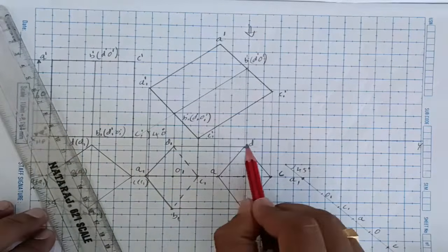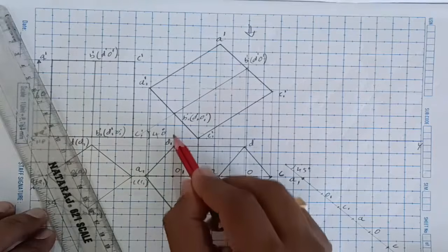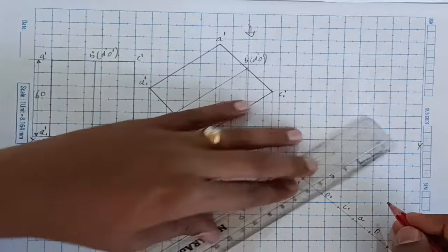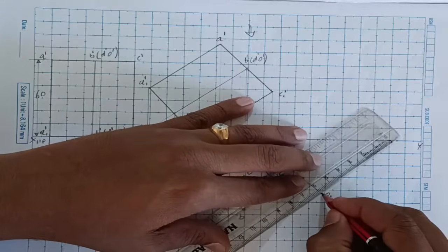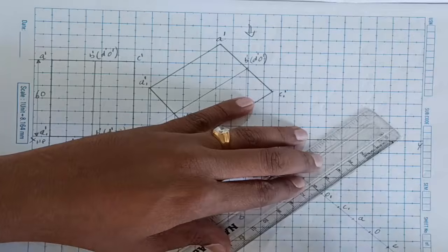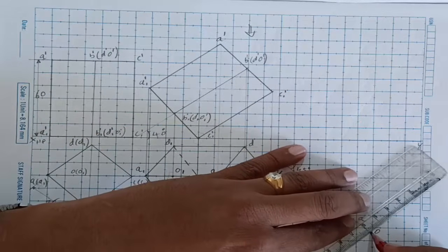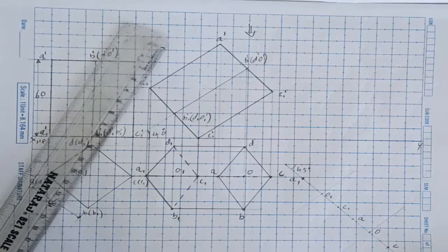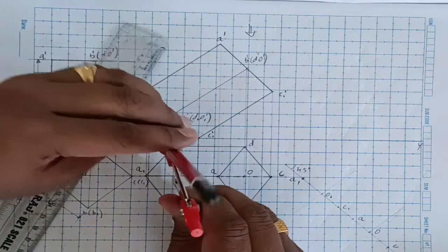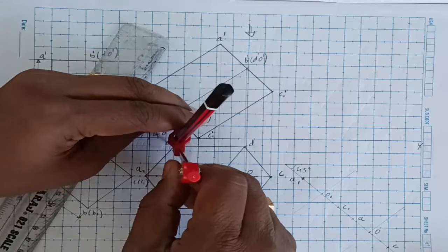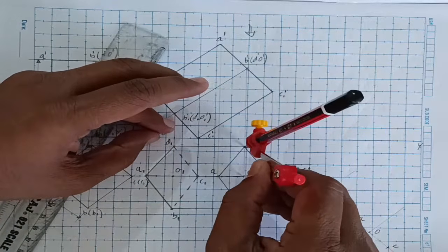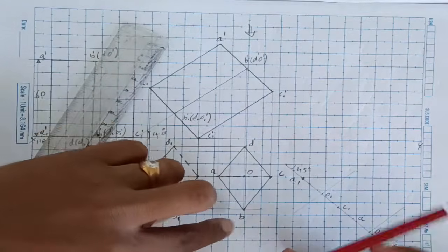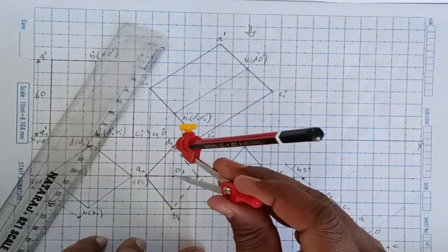Then to get the remaining D1, D, B1, B. On O1, if you draw a 90 degree line, because see this is a 90 degree line, we get D1 and B1. So that's why on the point O1, I will draw a 90 degree line on either side like this. And in the same way on O, I will draw one more 90 degree line on either side. So now I will measure the length, that is from O1 to D1. If you measure this length, all the lengths will be the same because it is symmetric. So the same length comes from O1 to D1, B1, and B as well as D. So once you measure one length, it is enough.